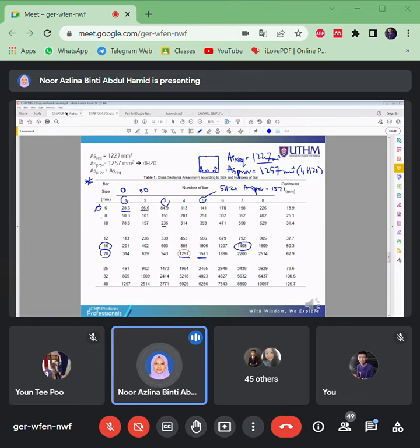Alright, so the AS that you provide should be more than the AS required. So I repeat, if you want to take 7 numbers of bar, a slightly smaller size like 16, but it becomes 7 here, how do you arrange this? The 7 bars will be crowded, right?